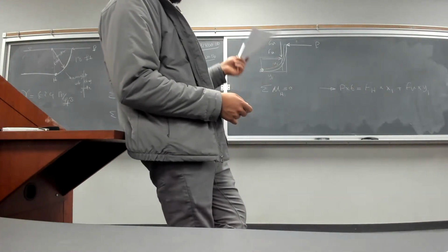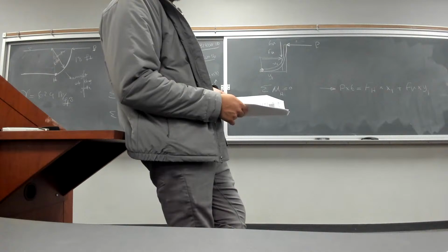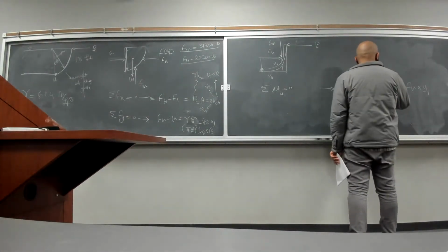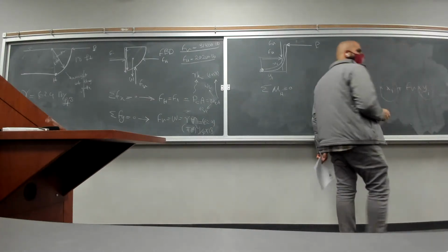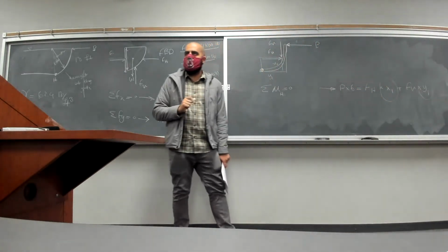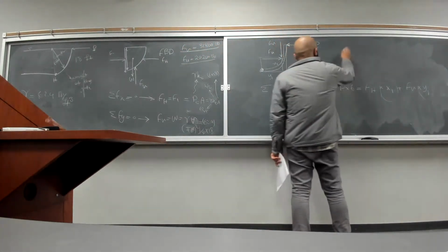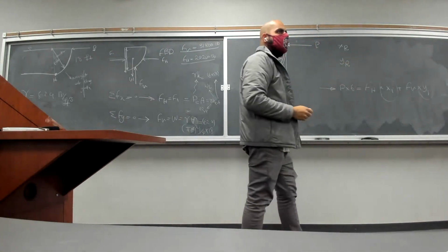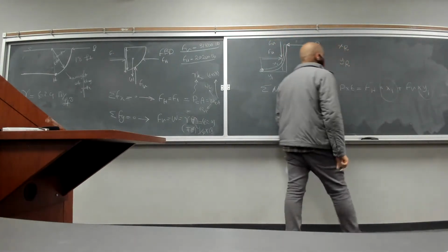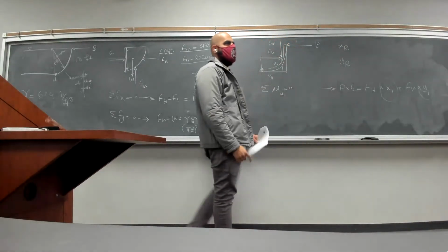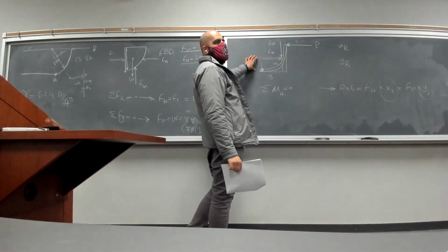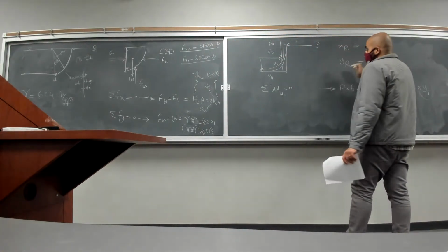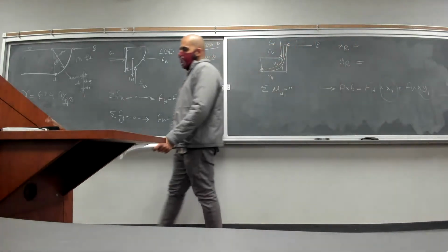So the next step is to find X1 and Y1. But how should we find that X1 and Y1? The idea was the resultant forces pass through the center of pressure, right? Remember that? We had XR and YR, right? So the arm these forces have to create that moment is actually the distance center of pressure has from this hinge, right? And if you recall, we had the equation for the center of pressure for the 2 points that identify the center of pressure